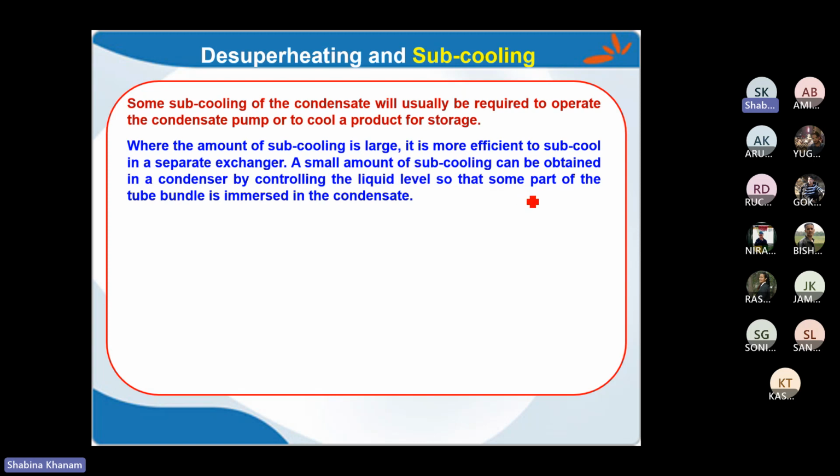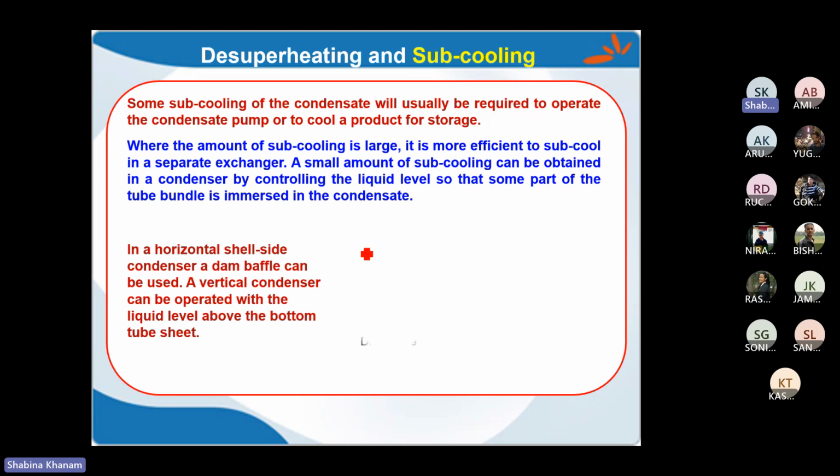Okay, a small amount of subcooling can be obtained in the condenser by controlling the liquid level so that some part of the tube bundle is immersed in the condensate. Okay, so certain amount of subcooling we require by making this dam baffle.